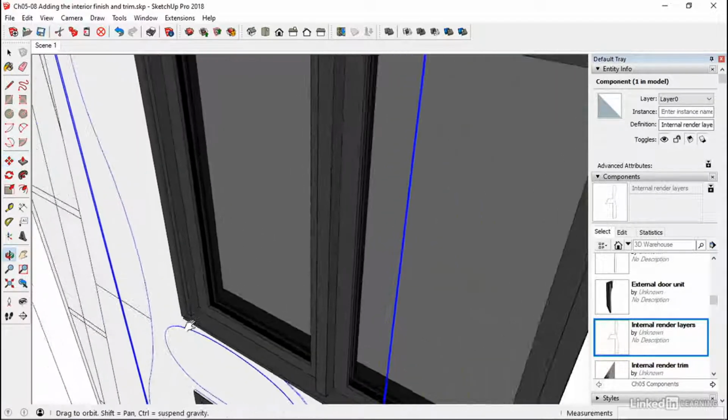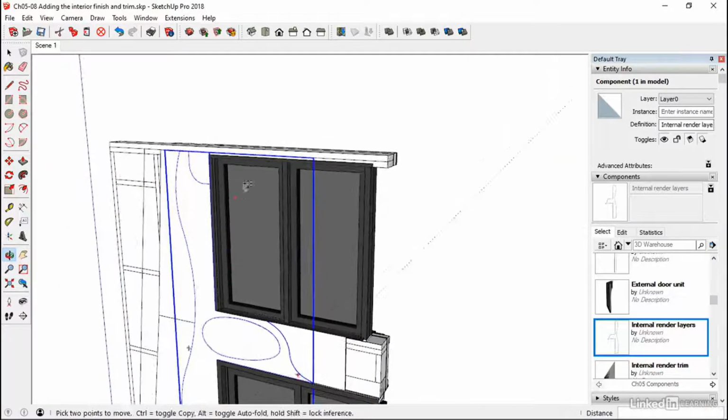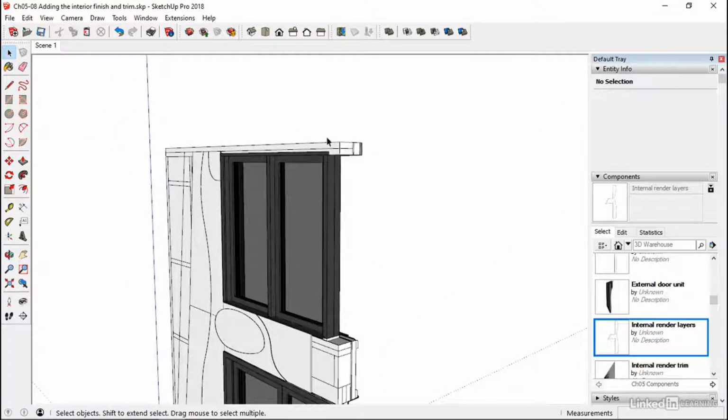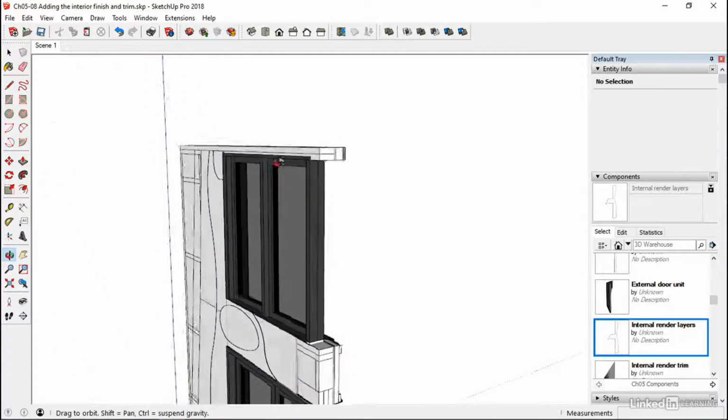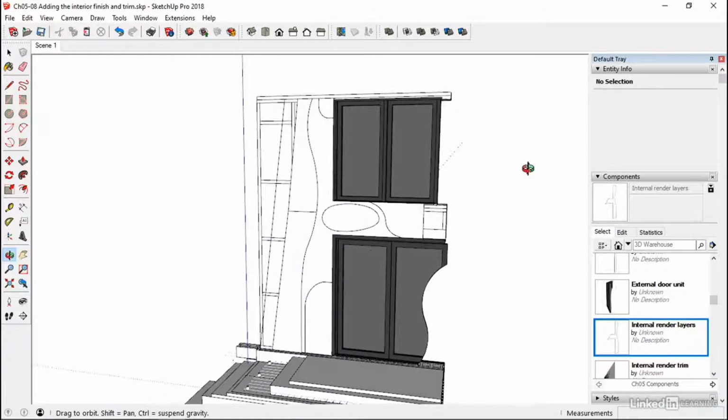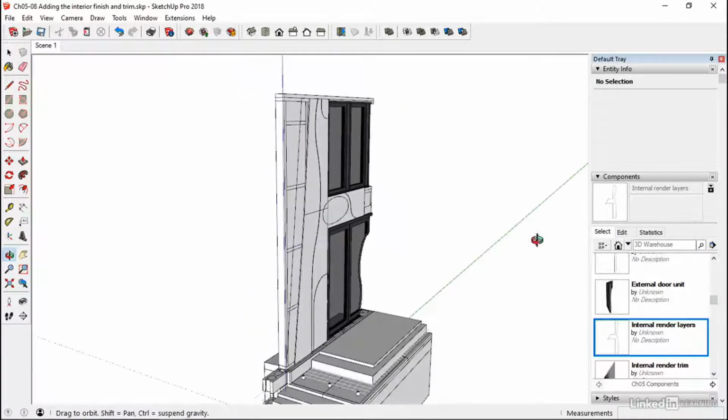Okay, now we might have a little bit to do at this point, depending on how this trim works with the roof joists and the internal cladding. I think I've got it so it's just about right on there. We might have to put a bit of mastic in there just to seal that little potential shadow gap at that point. But as far as everything else goes, we have now built up our wall, our internal layers. We've trimmed around internally.